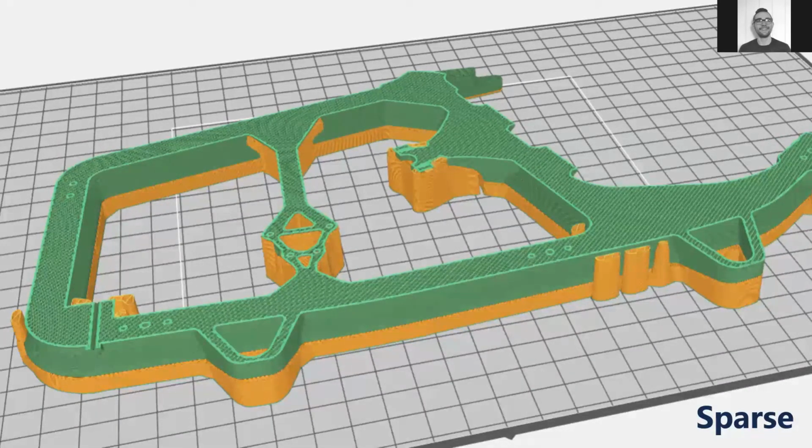Again, applying this globally, it'll be less material, less time to print, but may not provide adequate strength. Of course, we can adjust the layer parameters on a given set of layers, but as mentioned previously, those parameters apply to the whole layer. So if we're only looking to optimize one little section of a part, unfortunately, it means we're adjusting the layer parameters for that whole layer just for a specific area of said layer.